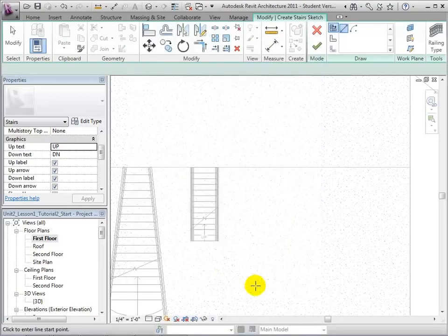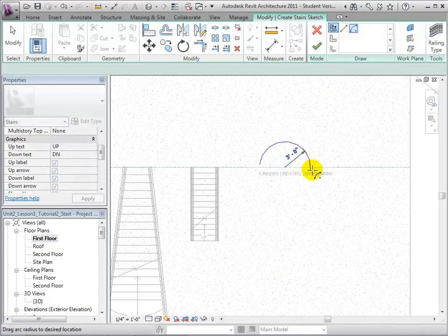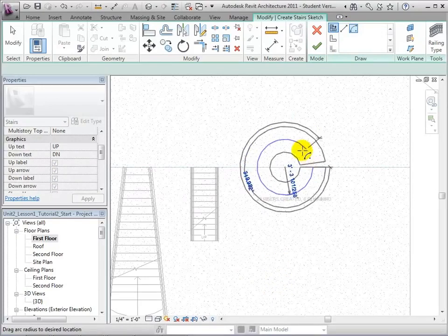Using this new type, we will begin placing the spiral staircase after selecting the radius of the spiral. However, Revit will not allow us to place a run line on top of another run line. Therefore, once 360 degrees is reached, the direction of the stair changes, or the riser count starts over. Essentially, the steepness of our stair type is too shallow to make a complete spiral.